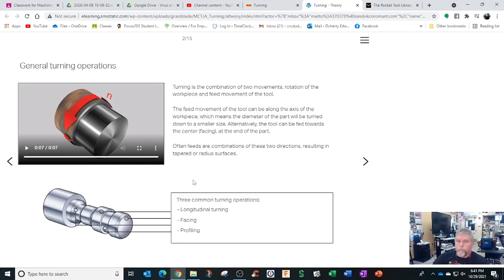On the lathe you can run in RPM or constant surface speed, CSS, also known as surface feet per minute. Whether you're in the Americas, it's going to be surface feet per minute or some other calculation. It's like if you laid out a roll of a round object and laid it flat: how many feet per revolution? You just do a calculation for that.